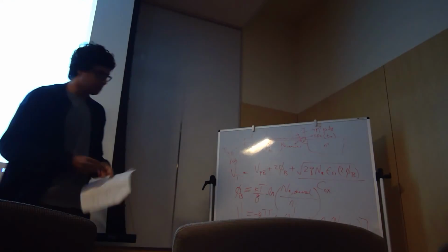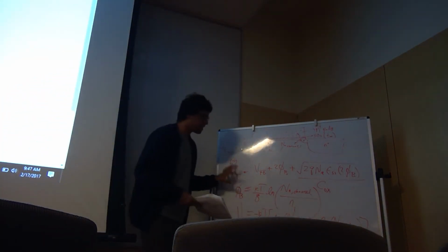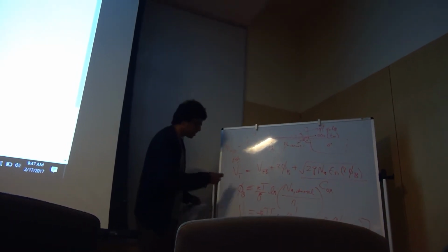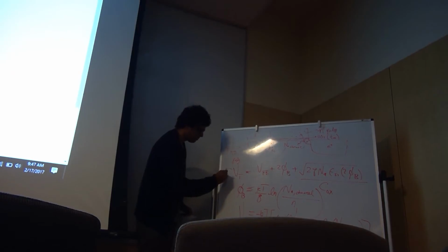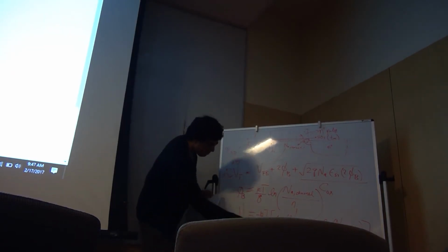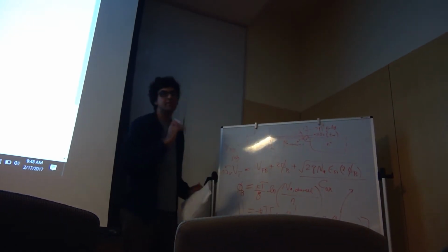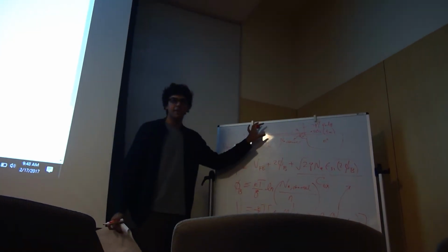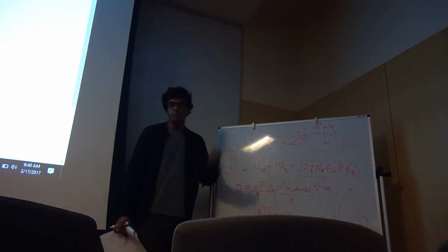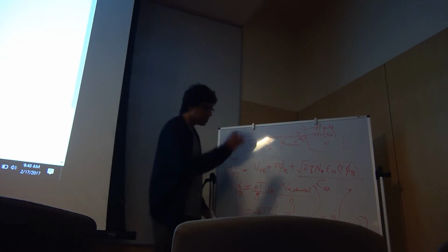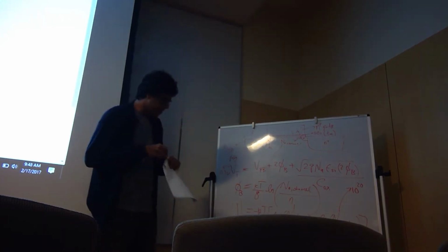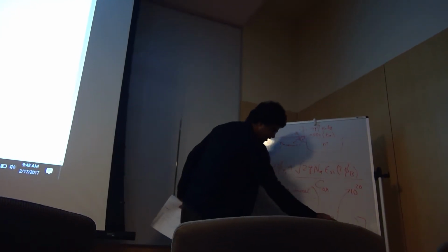So how would you solve this? Again, there are too many variables. You don't know enough variables to solve it. You know what the threshold voltage is because I've already given that to you. So say it's about 0.3 volts. So your flat band voltage will be something like this. You can assume your dopant, so your poly, okay? You want your poly to have minimum resistance as much as possible, so you try to dope this as much as possible. And because this is polysilicon, it can usually absorb more dopants than crystalline silicon. So you can assume this to be on the order of 10^19 to 10^20, okay? So assume some reasonable value here.